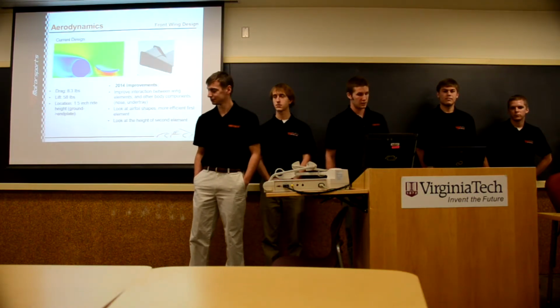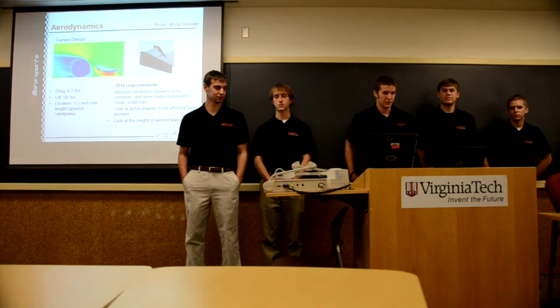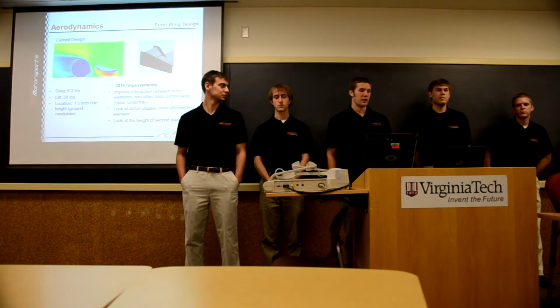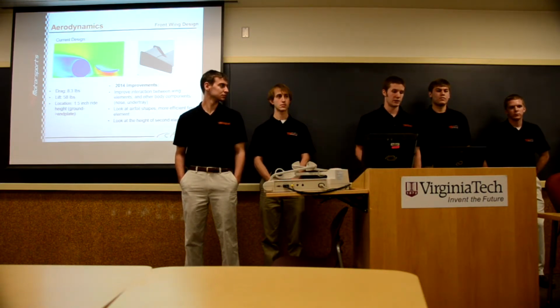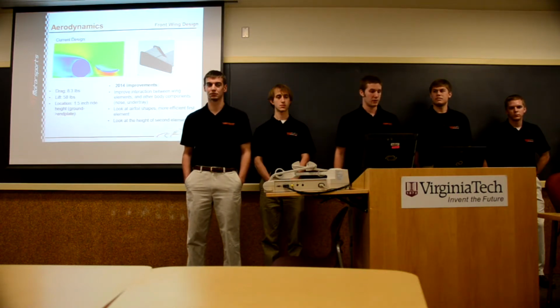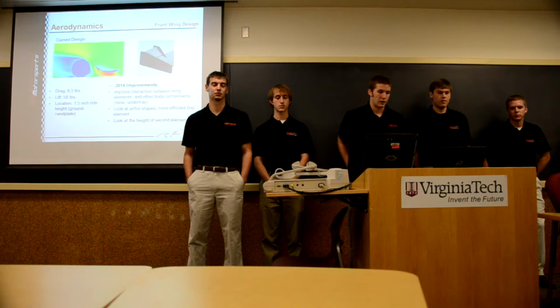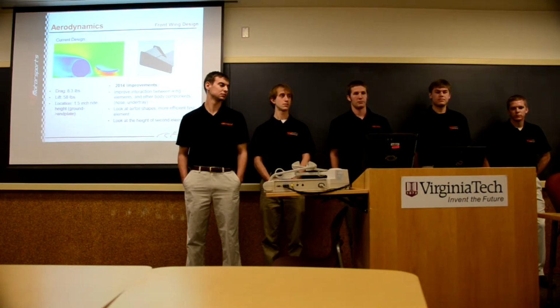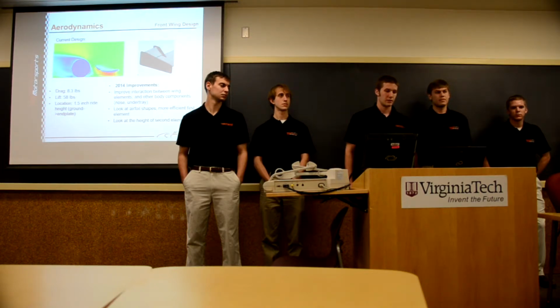Then for the front wing design, like I just said, we're able to produce 58 pounds of downforce. And the location right now, we have it at a 1.5 inch ride height, which is the height between the ground and the bottom of the end plate. And some improvements we're looking at for the 2014 design is to improve the interaction between the wing elements. Since we're going to have more time than we had for the 2013 design, we're going to look more closely at the placement of the second element,